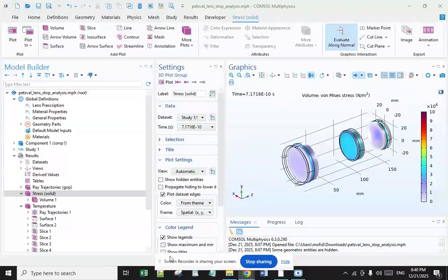It's worth noting that this thermal analysis models both the payload and the surrounding satellite structure. In many implementations, this may not be necessary, as the payload will be mounted in a manner that effectively thermally isolates it from the remainder of the satellite. In this case, the thermal analysis could be further accelerated by simulating only the optical payload, provided sufficient design and testing work has been done to ensure the payload can be treated as independent from the remainder of the satellite.